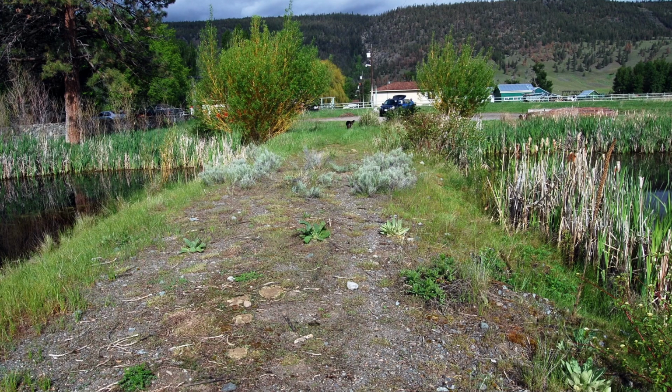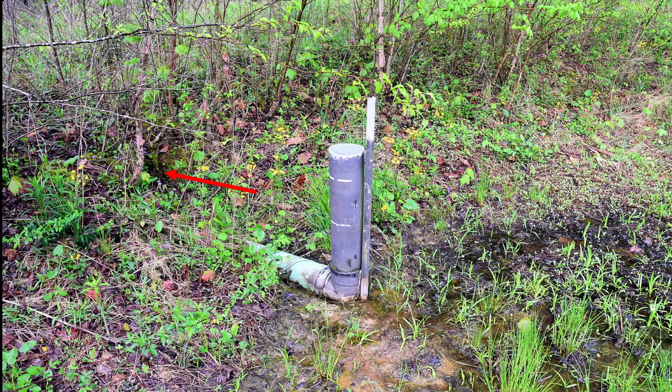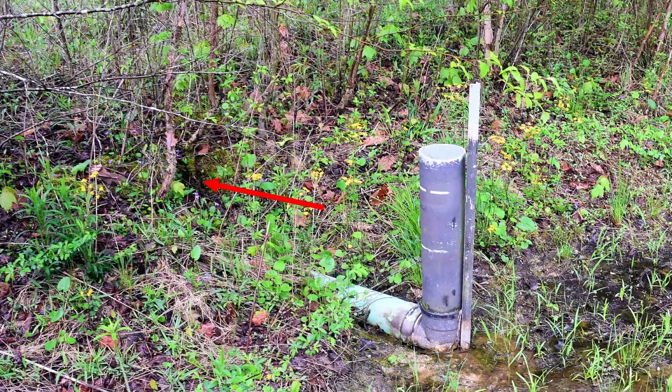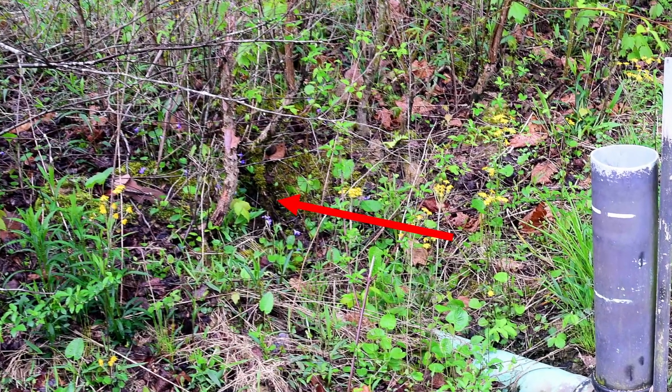Dams that have water on each side, like this one, are often riddled with muskrat burrows that enter from either side. At first glance, it looks like this water control structure is responsible for the almost dry wetland. Upon closer examination, I found where a muskrat had dug a burrow through the dam along the drain pipe. Water was flowing through this hole in the dam.